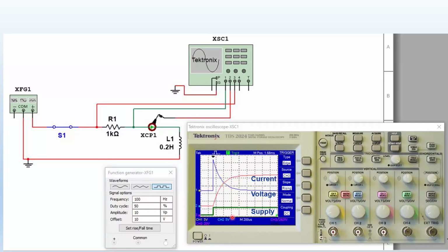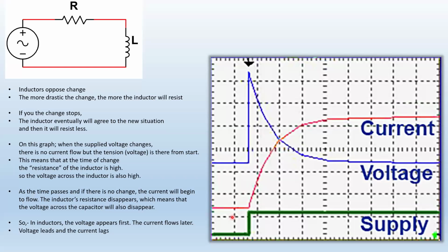Right. So when you apply frequencies, if you have a capacitor in the circuit, and you apply 100 hertz through the capacitor, you expose the capacitor to 100 hertz, and it is in series with some sort of a circuit, then it's going to let you pass the current. But if you increase the frequency to, say, 1000 hertz, it's going to let you pass the current even more. It's going to resist even less. So the bigger the frequency, the less resistance the capacitor is going to give you.